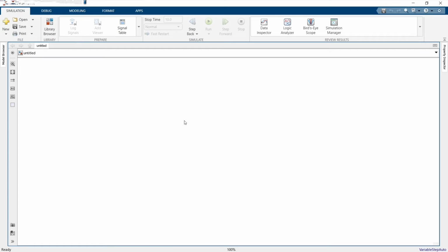I will name it V bat. That means voltage from the battery, the voltage reading from the battery. I also need another input, that is my V ref, my reference voltage or my full charge voltage. Okay, I require these two as my inputs. So I'll just rotate them. And I will be requiring an output. The output will be my duty cycle.